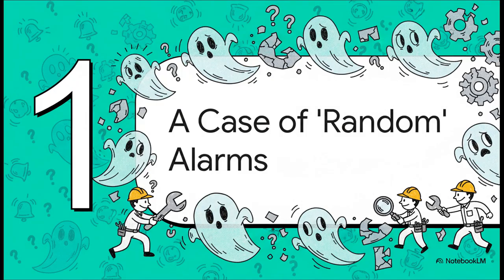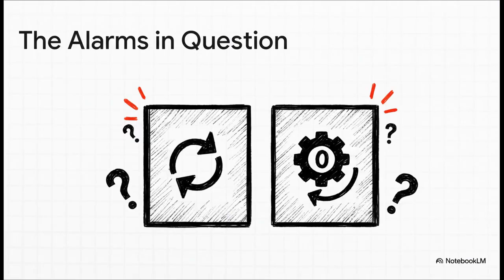All right, so let's zero in on the specific problem here. We're not talking about just any old alarm. We're talking about a very particular set of faults that keep coming back, forcing operators and technicians to basically chase ghosts around the machine. And here are our culprits. Alarms tied to the machine's turret, things like incorrect turret direction or turret needs zero return. They just pop up, you know? One minute the machine is humming along, the next it's dead in the water. This right here is the classic signature of an unstable system.